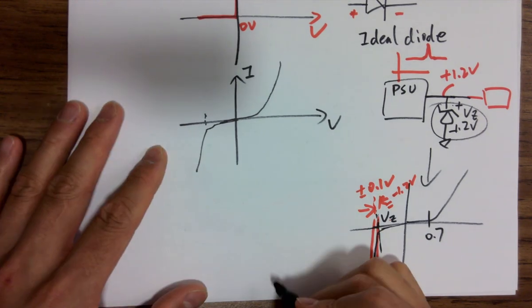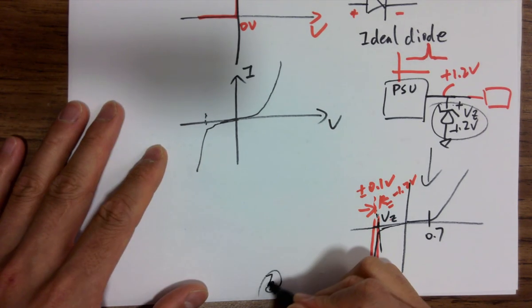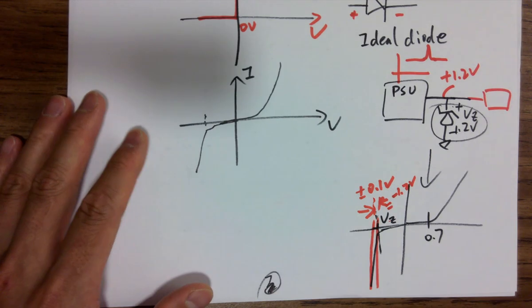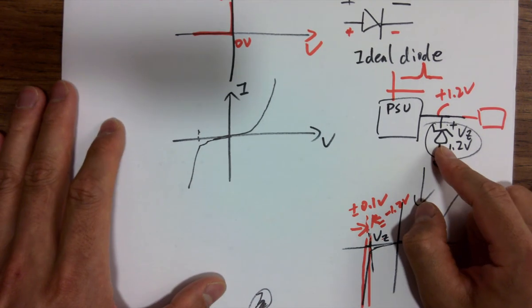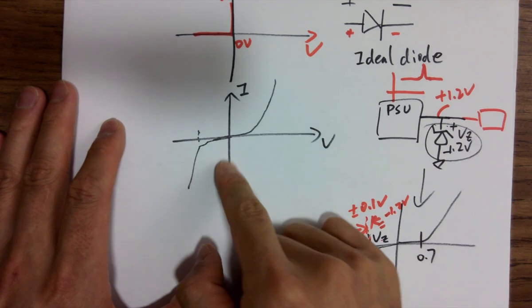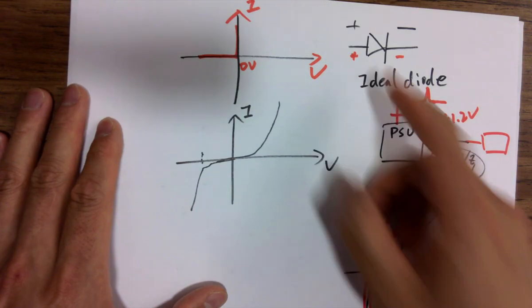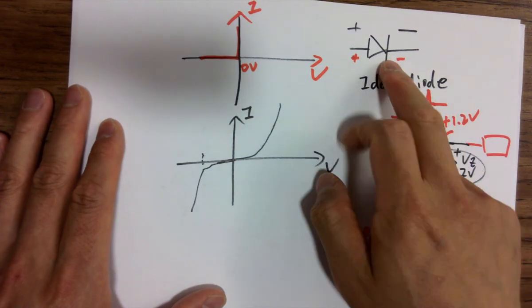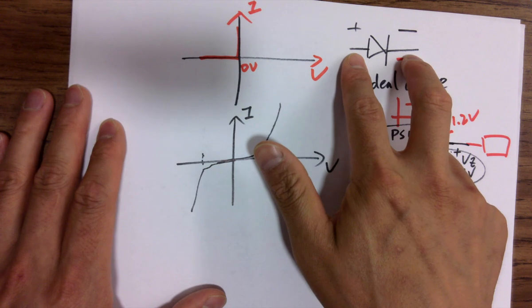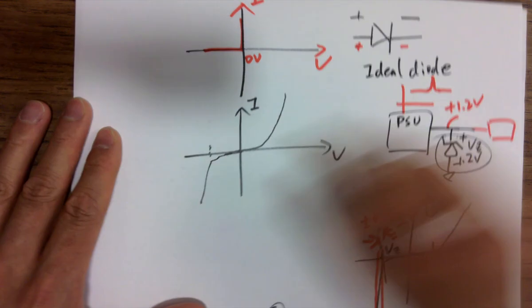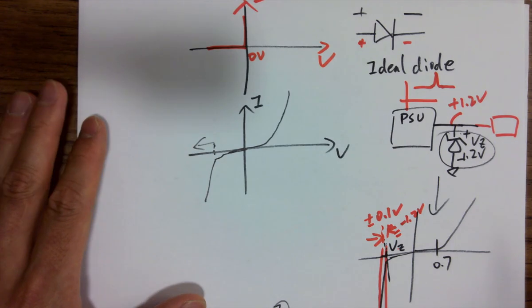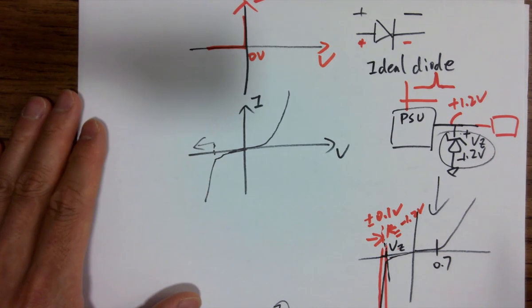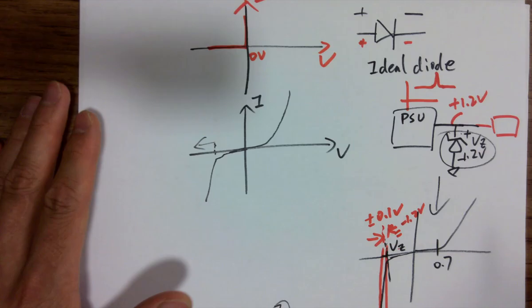Is that the same as a regular PN junction? No, good question. For a Zener diode, they have different dopants and different concentrations. That's why it performs differently from a regular diode. It's more expensive as well. With a regular diode, if you do reverse biasing, whenever it goes beyond that voltage in a negative way, it breaks down. It's broken. You cannot recover it.